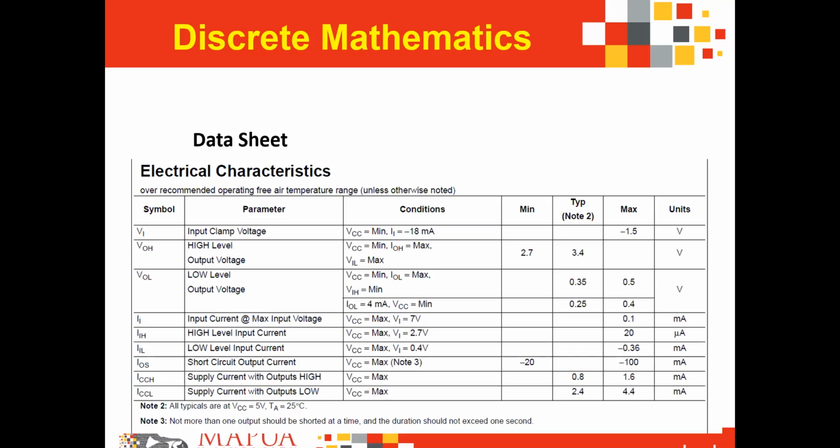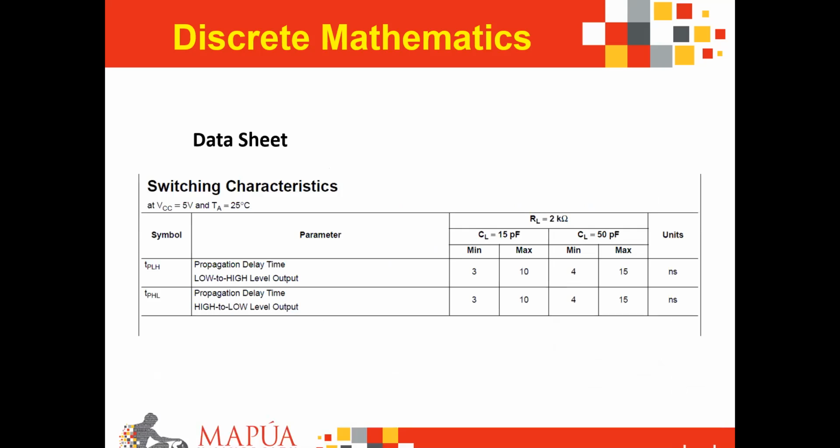There are electrical characteristics regarding your ICs, which show you how many inputs can be connected at the same time, and what would be the corresponding rating of currents circulating in your ICs the moment you connect these devices. Likewise, you also have switching characteristics, which show how fast your corresponding transistor-to-transistor logic operates the moment input values change instantaneously.